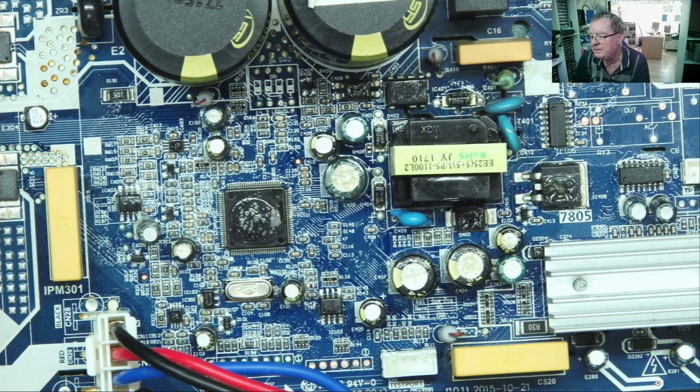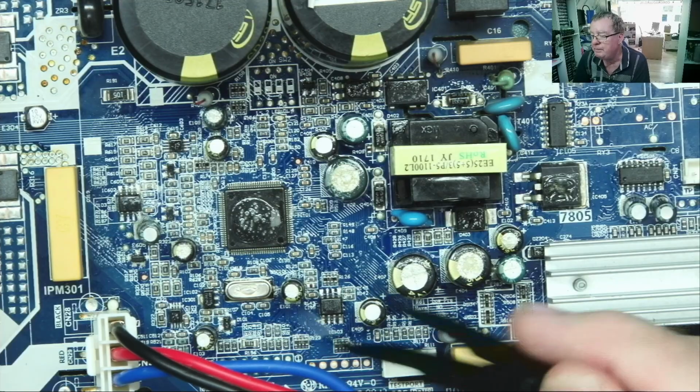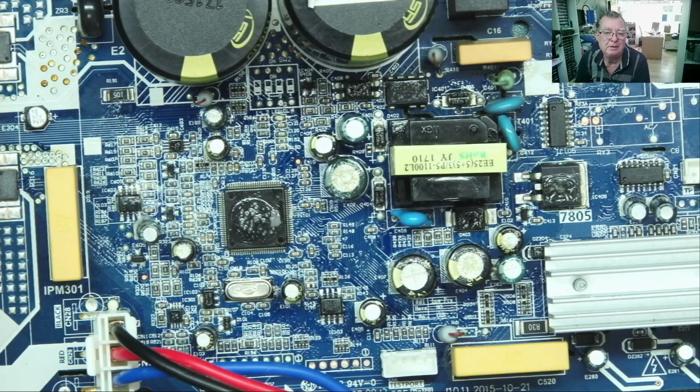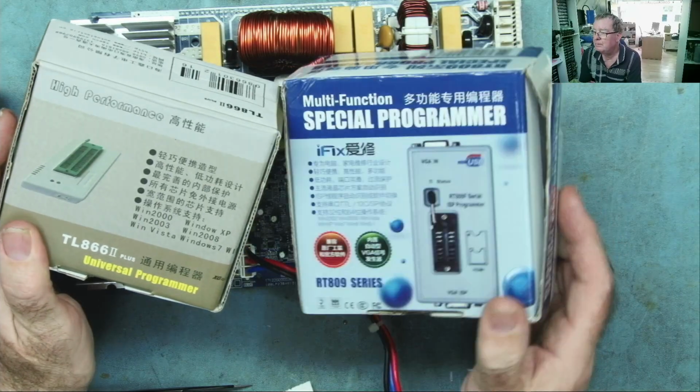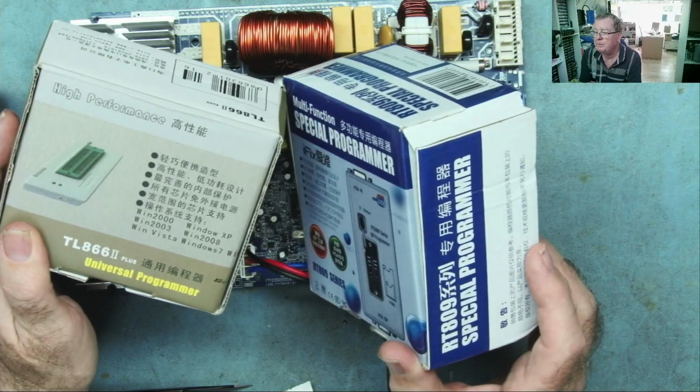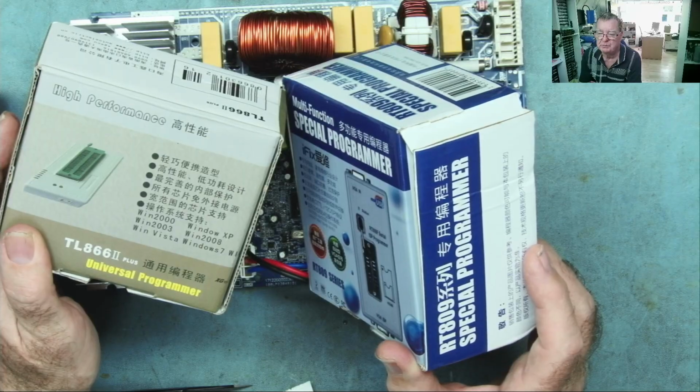You probably need to remove, in the case of an EEPROM, the chip from the board, get into a programmer, have a look online, ask around. Maybe you need to find another device of the same type and remove that chip. You're going to need an EEPROM programmer, often more than one, because some programmers will do some things, others will do other things.